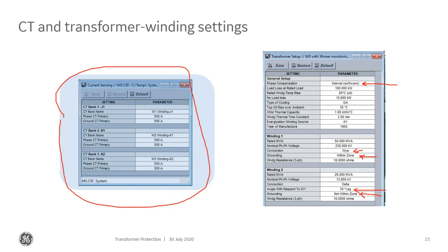A compensation matrix usually looks something like: A phase current is going to be equal to 1 over the square root of 3 times A phase current that's measured, minus 1 over square root of 3 of B phase current that's measured. The way that the matrix is calculated is based on how the transformer is actually wired. So it's using a combination of the currents to get that phase shift back.